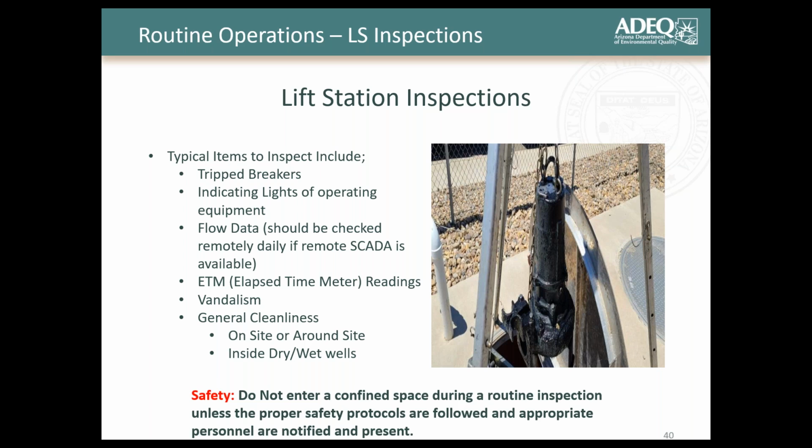Keep in mind, lift stations and wet wells are still confined spaces, so do not enter a confined space during routine inspections. This is very common. I've seen a lot of folks try to enter, especially lift stations that have wet well and dry well combinations. People feel a lot more comfortable walking into a dry well. Well, it's still considered a confined space, and depending on the setup or the way it was built, you need to follow the proper safety protocols. Notify the appropriate personnel, and make sure other folks are present. You definitely don't want any confined space hazards at a lift station to affect your life.